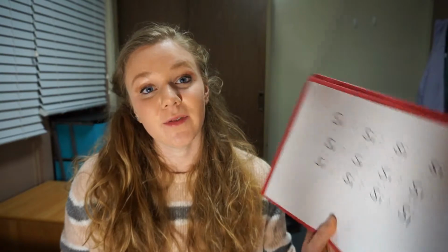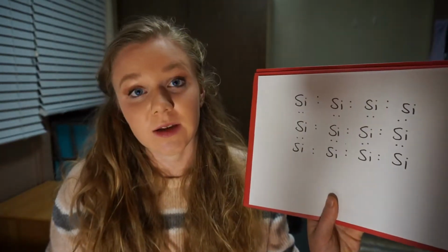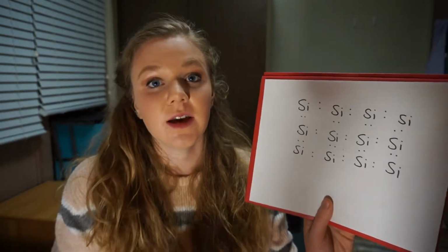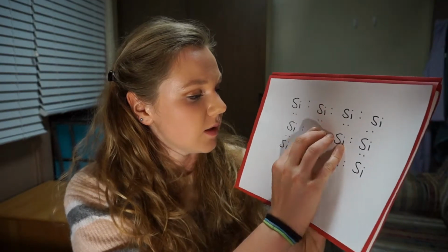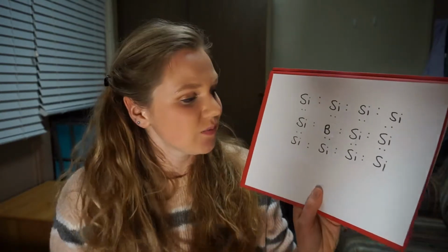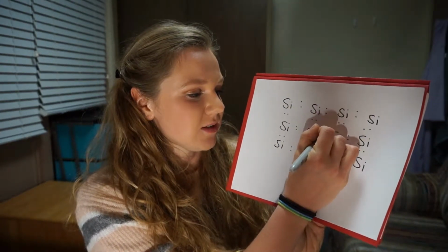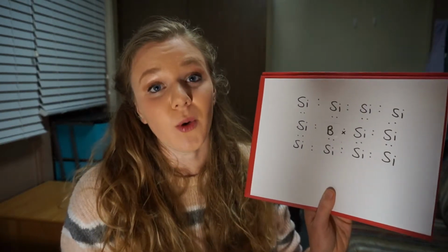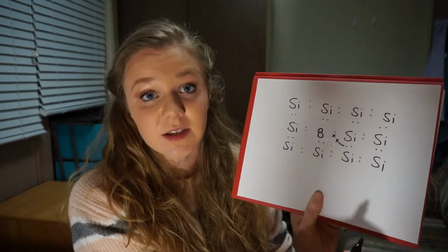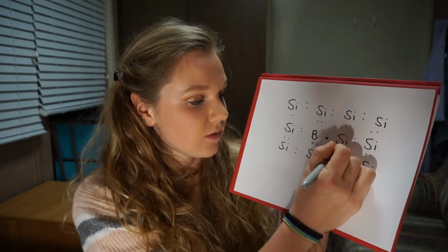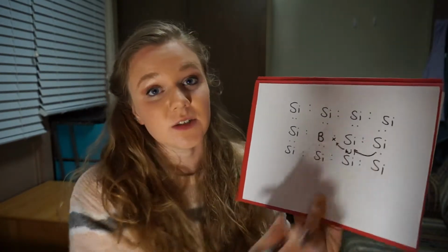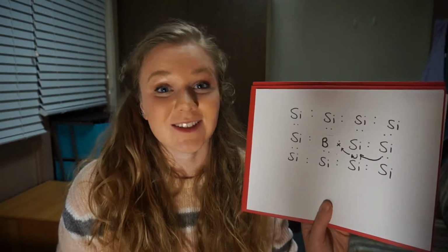What that means is if we again take a look at our silicon lattice, and we instead replace one of the silicon atoms with an atom that has one less electron than silicon, say boron, then instead of having an extra electron to add to the system, it's missing one of these electrons. That causes what's called a hole, which an electron can move to fill. The electron from the silicon atom might move into that hole, which might cause another electron to move there, which might cause another electron to move there. And since we do have movement of electrons, that's conductance.